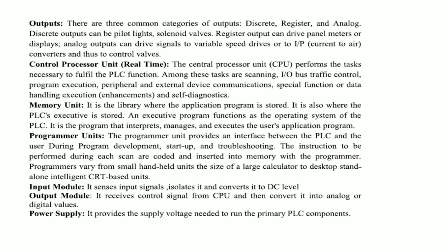It is the program that interprets, manages and executes the user's application program. Programmer unit: the programmer unit provides an interface between the PLC and the user during program development, startup and troubleshooting. The instructions to be performed during each scan are coded and inserted into memory with the programmer. Programmers vary from small handheld units the size of a large calculator to desktop standalone intelligent CRT based units.